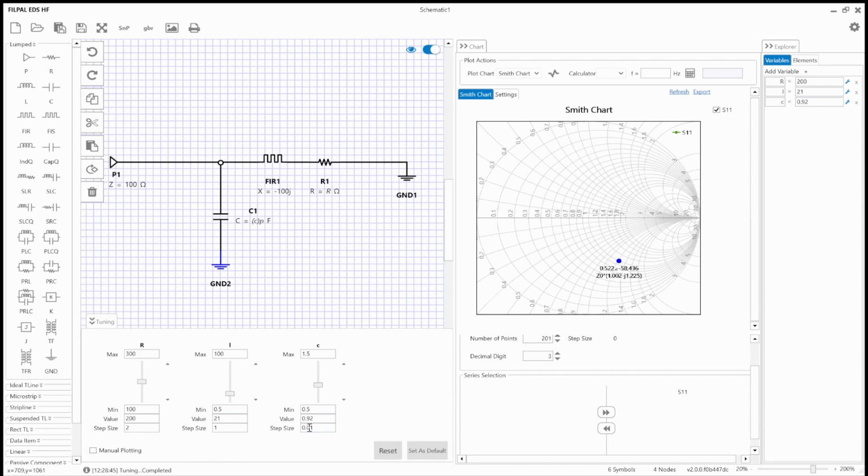You can try to adjust further, like maybe put 1 more, and then you go until you reach 1, all right? So you have already found the value of a capacitor, which is 0.923 picofarad, to move in clockwise direction from here to here. And how do we move from this point to 1? You see that it's going to be in the clockwise direction. So I need to use an inductor, because inductor will bring me there, right? So this is L, and then this, maybe I can put it 1 nanohenry.